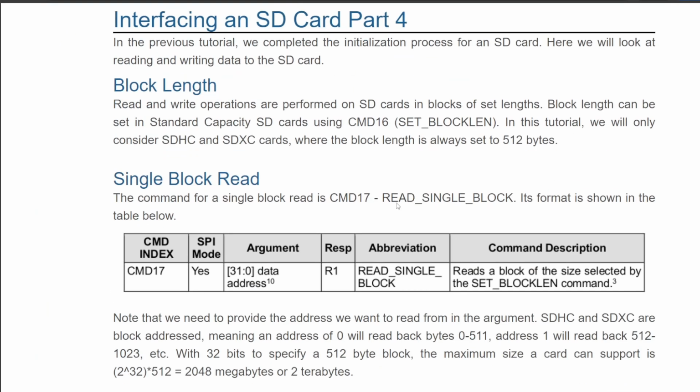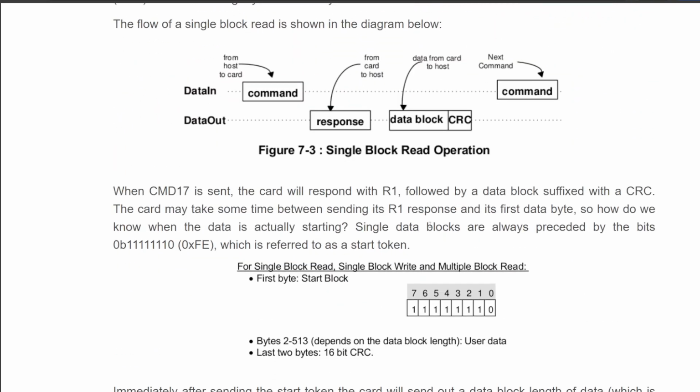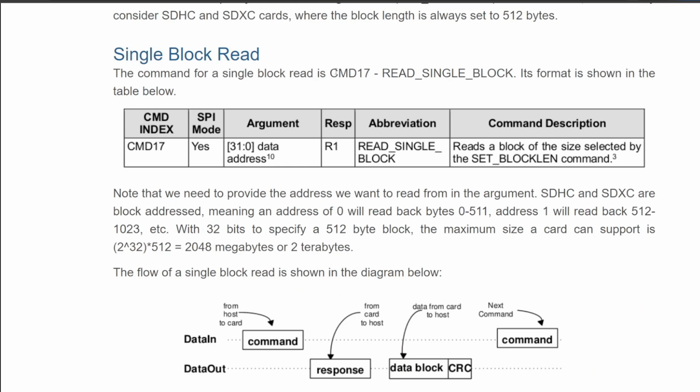Right, so now we're getting to the real interesting bit. So we've finished the initialization, and now we're going to try reading a block of data. Command 17, read single block.